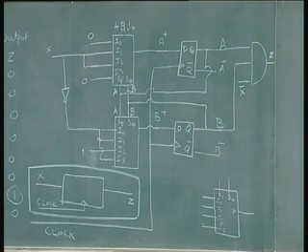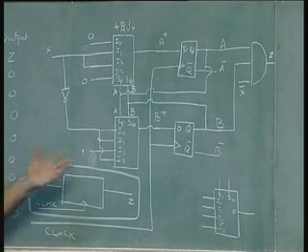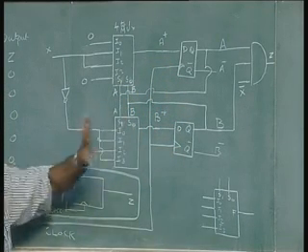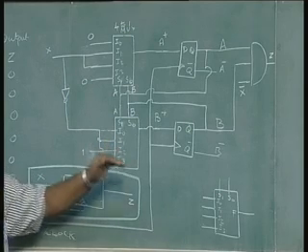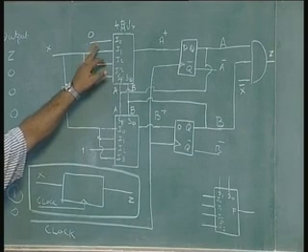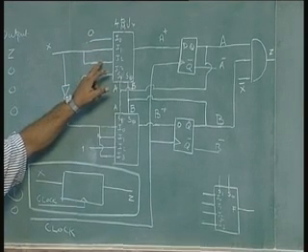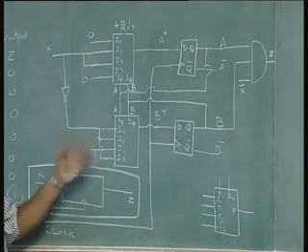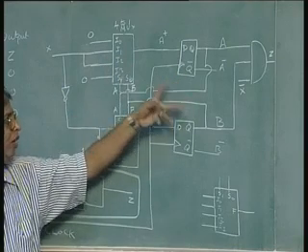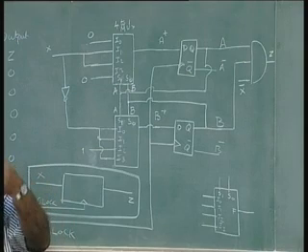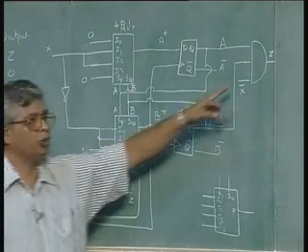This is a very simple design for two reasons. Reason 1, this part of the circuit is the same. Any design up to 4 states will have the same 2 multiplexer architecture. Only the inputs to these multiplexers will be different. So, for the given architecture with 2 flip flops and 2 multiplexers, I can design any 4 state machine. Of course, the combination logic of the output also will be different.